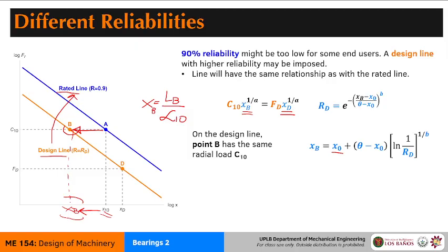If the manufacturer cannot provide it, then either we buy a lot of bearings from their company and perform the test ourselves, or we just assume a particular set of distributions. But again, the latter choice is not very safe. So this is XB. This is the formula for XB. Normally, let's say we would know our design force. We would know also our design life.